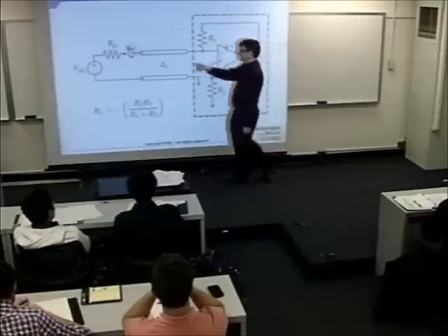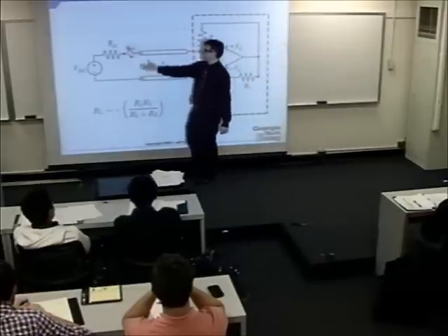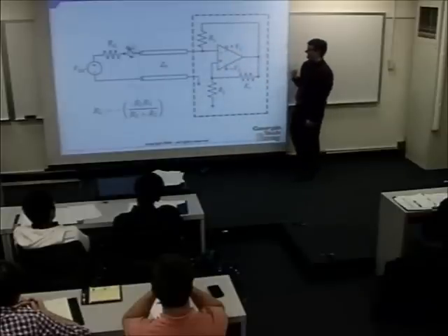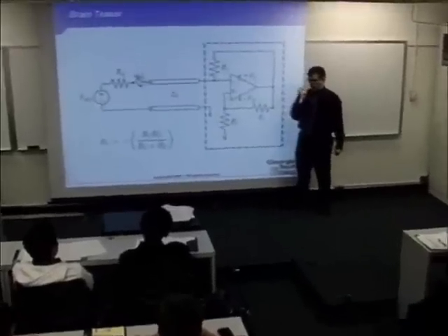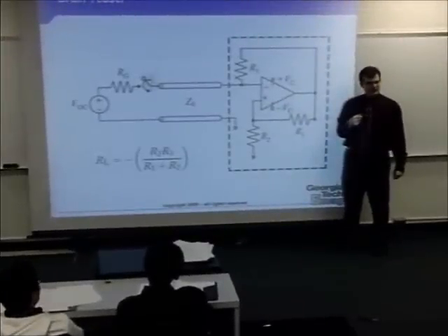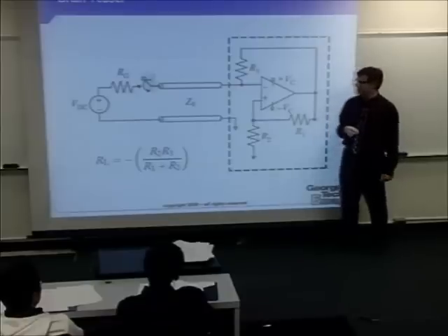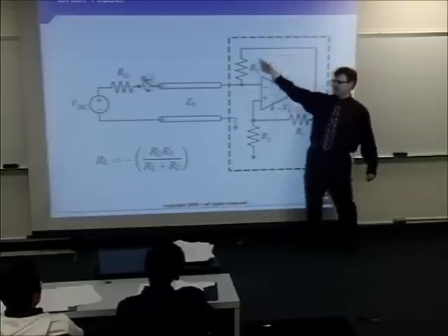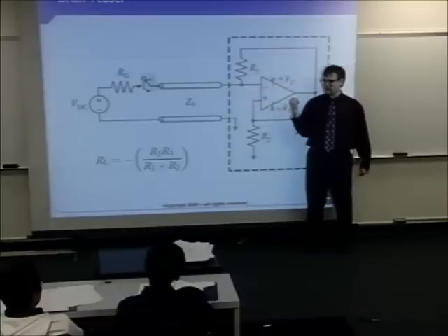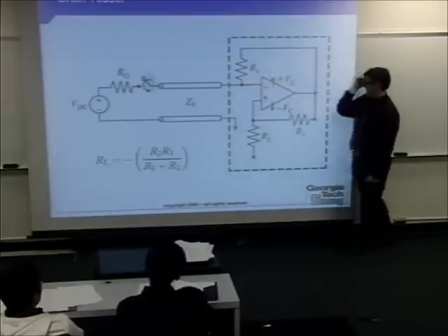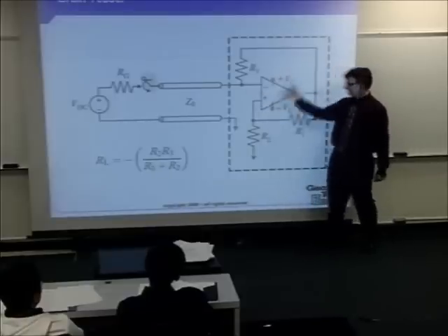You got a DC source and a resistor, switched it in, and over here is this crazy op-amp circuit. And this is a really nice 3041 problem probably, or I don't know, what class do you study op-amps in? 3042, 3041. Probably you see it a couple times in various classes. Well, you see, I got my negative feedback there, right? And you can use your assumptions for the op amp that there's no voltage drop here because it's got negative feedback, no voltage drop, no current going into the op amp. This voltage will be whatever it takes to make this system work this way.